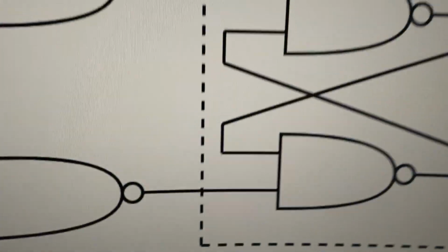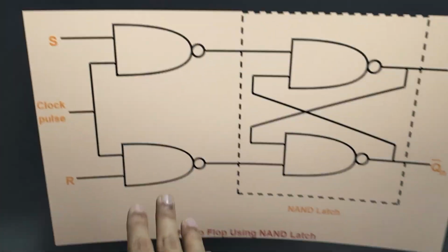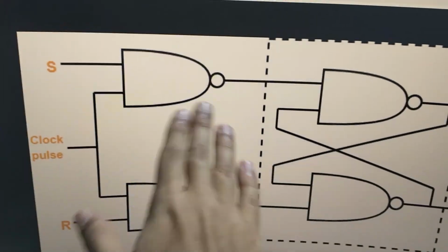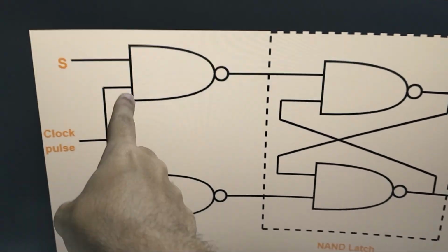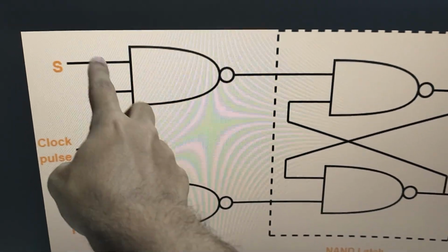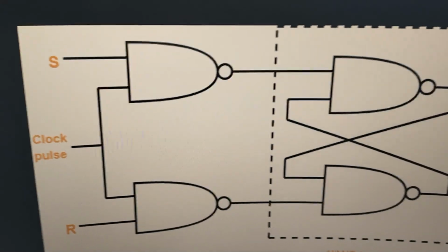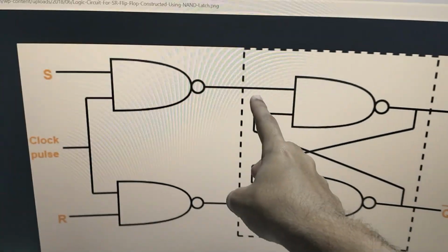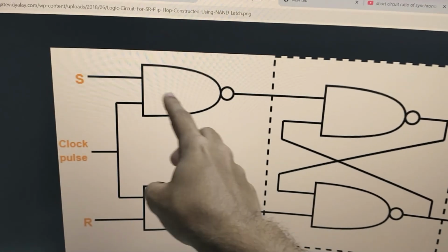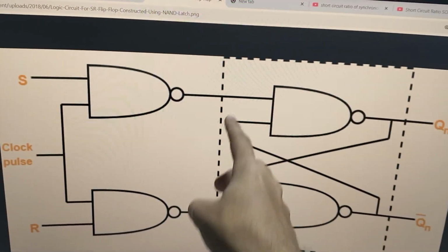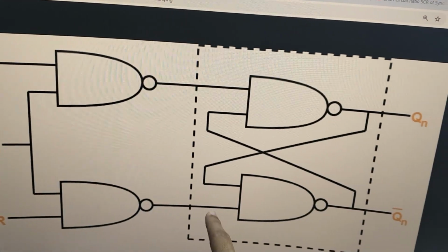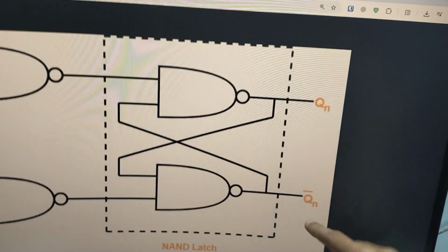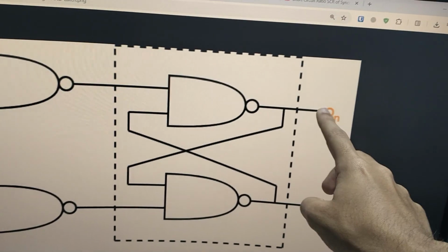so that's good too. So here I'm going to be using the latch, not a flip-flop, so there's no clock, it's not clocked. So we're just going to short these two inputs and call it set, short these two and call it R. And this one will basically receive S bar, which is the complement, since if you short the inputs we are going to get S bar, and if you short these two you're going to get R bar. And that is going to give us the output, and the output complemented, and we'll only be dealing with the output.